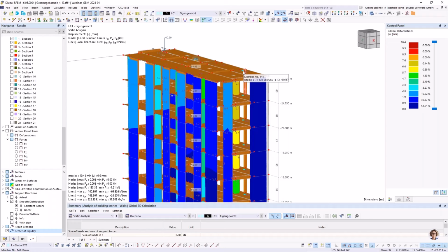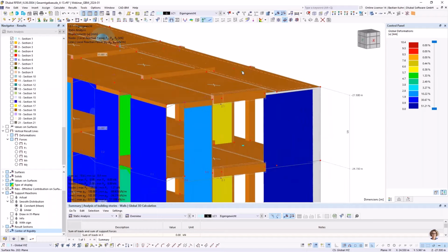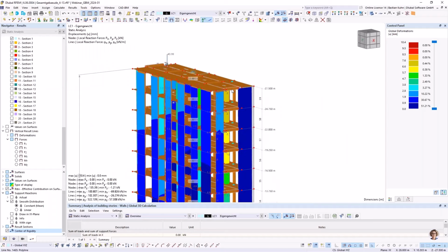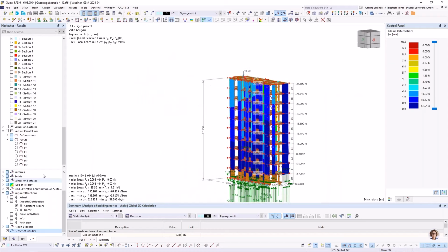And this is actually something for when you are doing a dynamic analysis, which would also be possible with this add-on. It would regard your eigenvalue analysis due to the response spectrum method, and you would get the force in every story, and you could regard torsional effects by introducing load on the stiffness center, because if you introduce the load on this point via the eccentricity to the mass point, you can regard torsional behavior of the structure perfectly. You have that in each story, here, here, and here. Okay, this is one of the advantages of the building model.